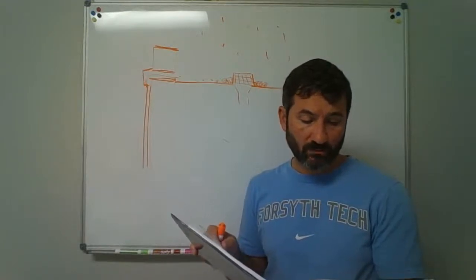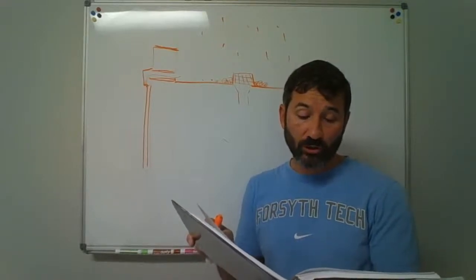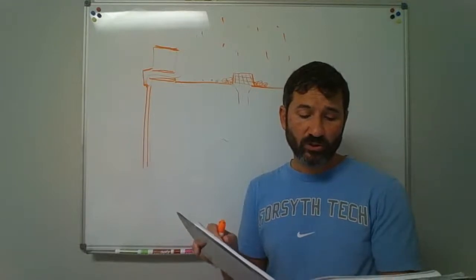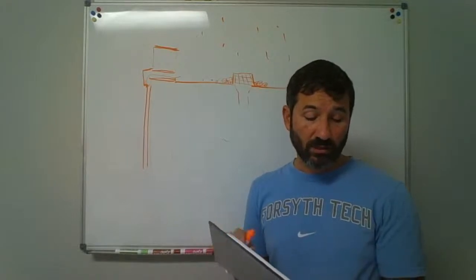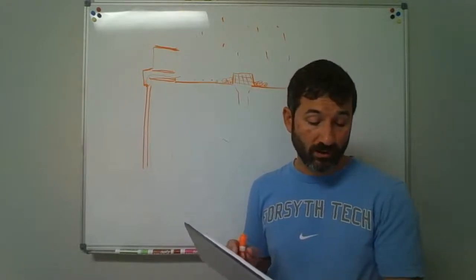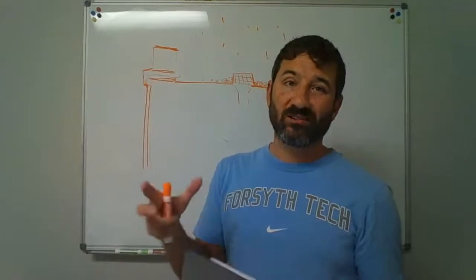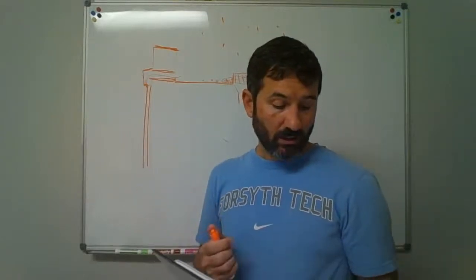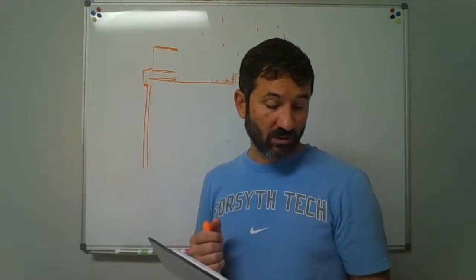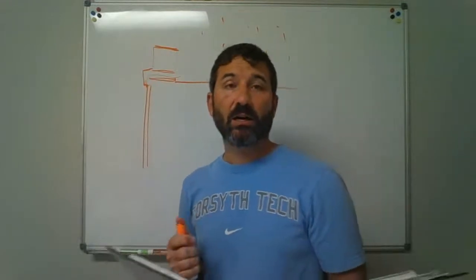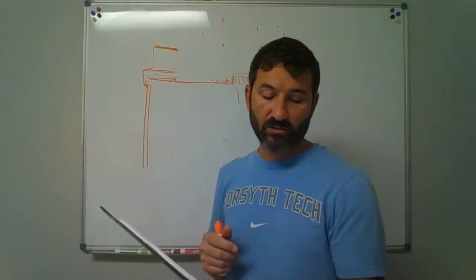Subsoil drains, building subdrains. Building subdrains located below the public sewer level shall discharge into a sump or receiving tank, the contents of which shall be automatically lifted and discharged into the drainage system as required for building sumps. The sump and pumping equipment shall comply with section 1113.1, sumps and pumping systems. So if you're collecting this stuff and it's below where you're going to be, you can collect it and pump it up and out. Pumping capacity and head: the sump pump shall be of a capacity and head appropriate to the anticipated use requirements. The sump pit. These are very much like a sewage ejector pit that we've talked about previously in Chapter 7.